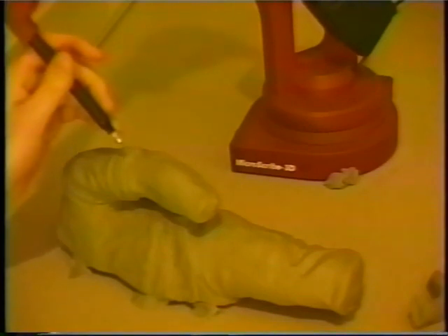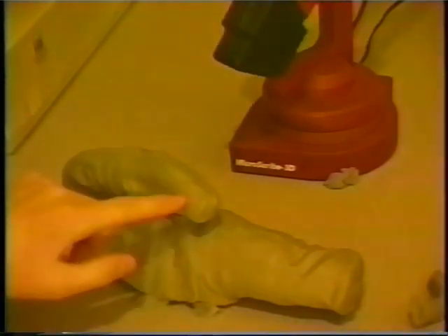When I'm done, I hit another key and make a line out of it. In this case, it's a NURBS curve is what we've made. When you're digitizing, you don't want to drill the tip too far into the clay, because that'll make a dent, and obviously you won't get an accurate reading of the surface. We continue on making the curves, and after the curves are brought into Softimage, we can skin them together to make the surface.